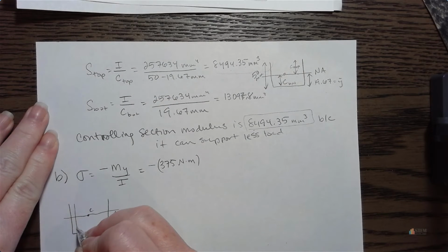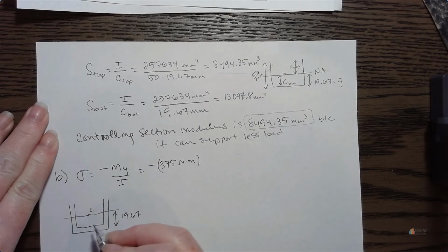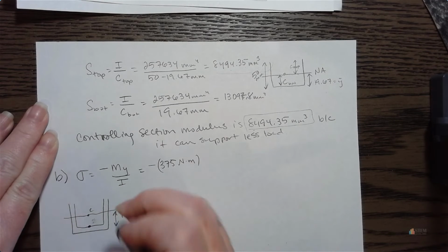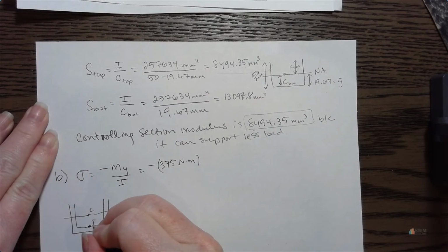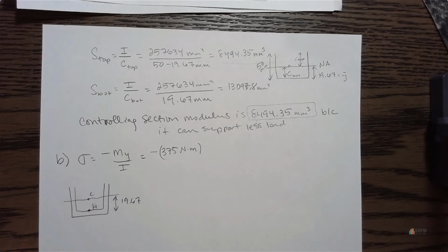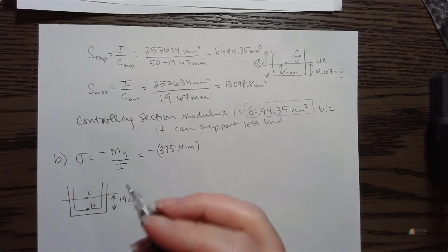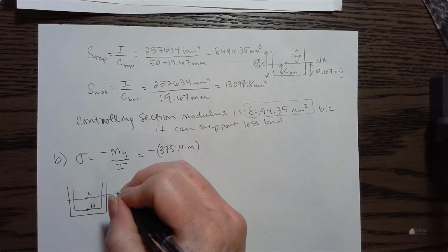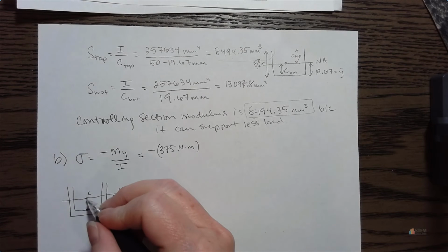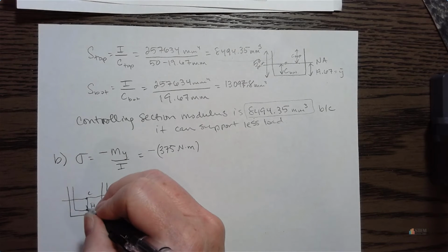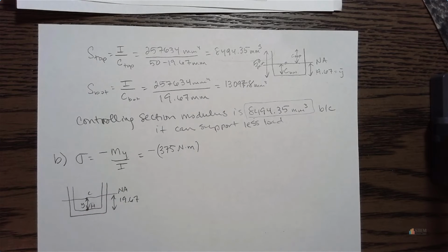Let's draw this little picture a little bit better. Okay, so it looks like this. B is right here. Or not B, I don't know why I called it B. We're on part B, but we're looking for H. All right, so let's change that to H. Okay, so there's H. Now, Y is the distance from the neutral axis, which is right here through the centroid, to H. Okay, so this is going to be Y. All right. Now, if we're below the neutral axis, we're going to say it's a negative Y value. If we were above it, we would say it's positive.